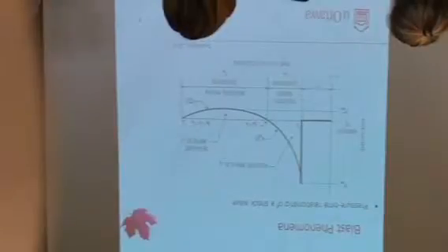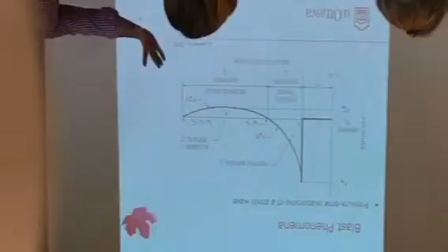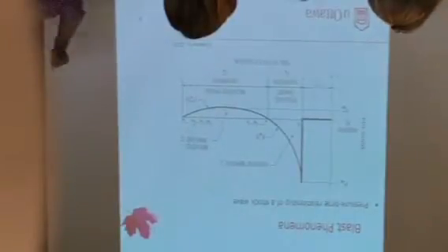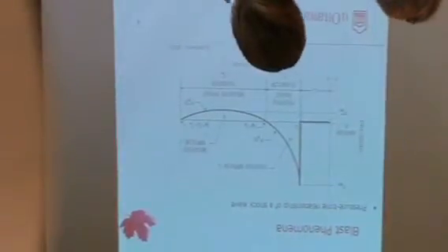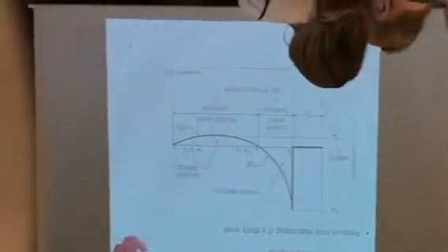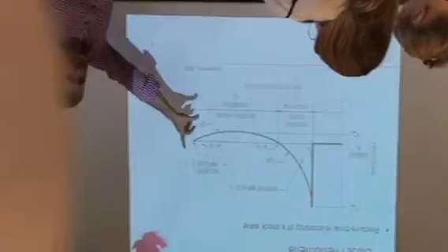When the blast comes, it doesn't do damage to the window, but when you have the negative phase, you can easily withdraw those nails or screws, right? So you have to design it for both. If you have a column, and it gets hit by a positive phase and then a negative phase, you say, okay, I will only design it for the positive phase, and I should be okay. But this is the actual shape of the blast load.